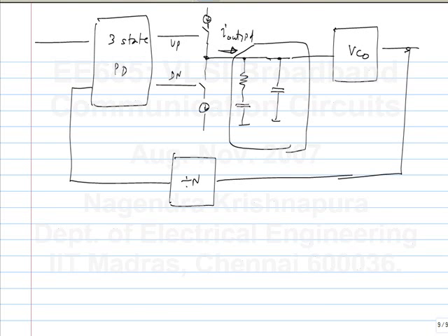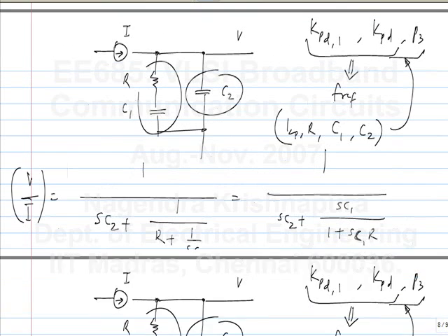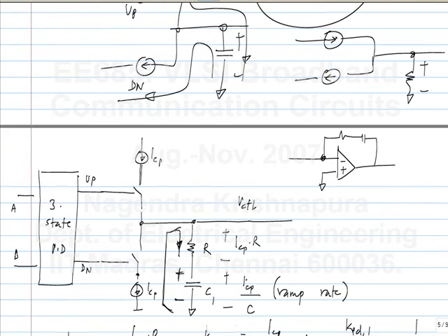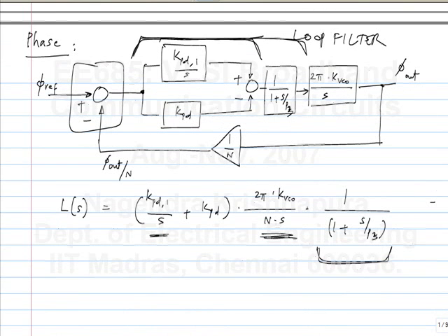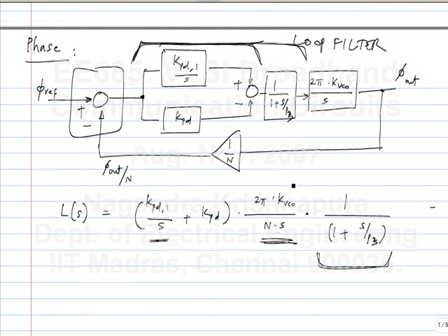So this is the model, and originally what we had was we didn't have the integrating path, but we had the rest of the stuff. And the phase detector was ideally modeled by this, but in reality it also had an additional input, E of t. My question is, what is E of t in this particular type 2 PLL? In case of type 1 PLL, we found the phase difference, we found that it was some kind of square wave, and we found what its amplitude was, etc. What is E of t in this case?